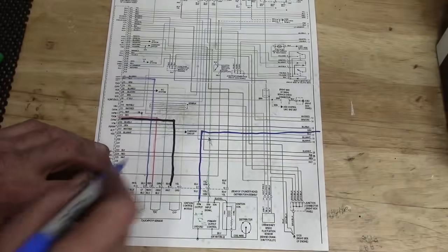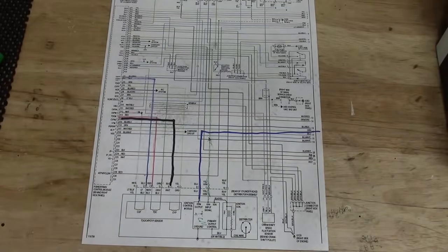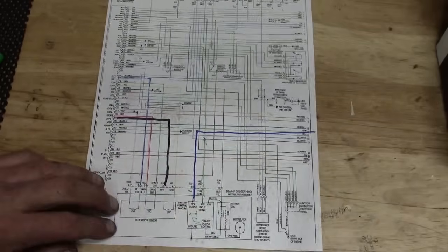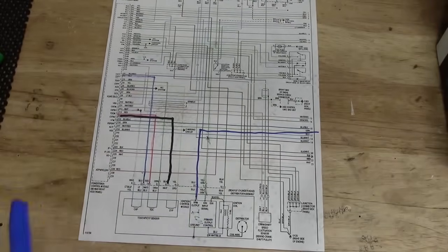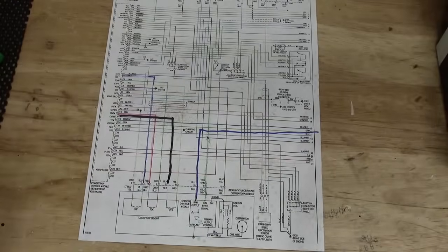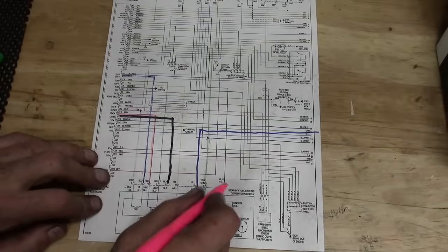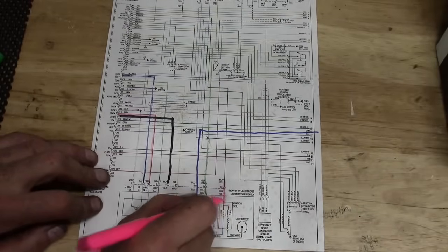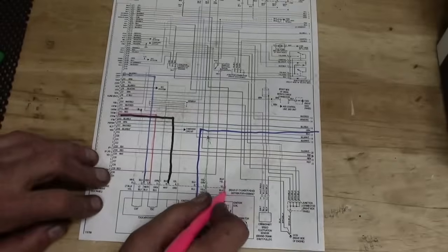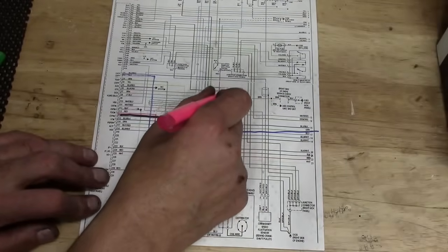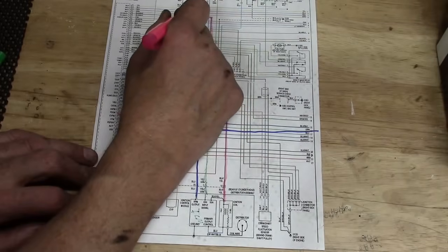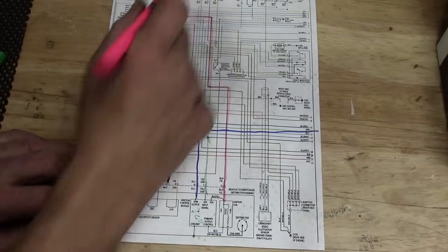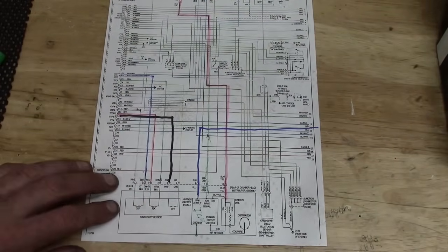And now I'm wondering, bad ICM, not seeing the RPM, if that could be a factor there. I don't know. What else do we have coming out? We've got to have our power. We have not had a power come in yet. And that I know is that black and yellow wire, right? That's the very first thing we did. There he is right there. Black and yellow wire. And that goes right to powering the ignition coil, which is also in this assembly. That is going to go right up to a fused power that is going to be on with key on. All right. It says on or start up at the top.